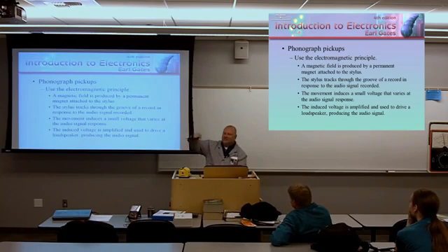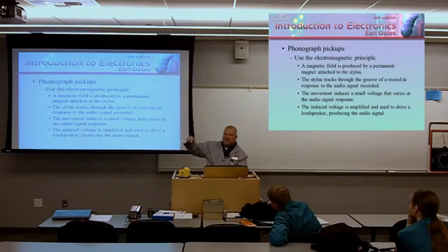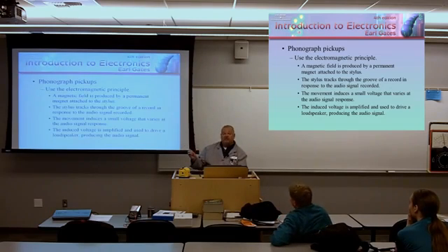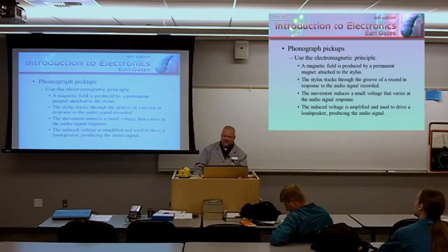But the stylus literally tracks through that groove in the record in response to the audio signal. The movement creates a small voltage that varies with the audio signal to replicate the wave pattern that originally created it. The induced voltage is then amplified and used to drive a loudspeaker, producing the audio, a facsimile of the audio signal that produced it.